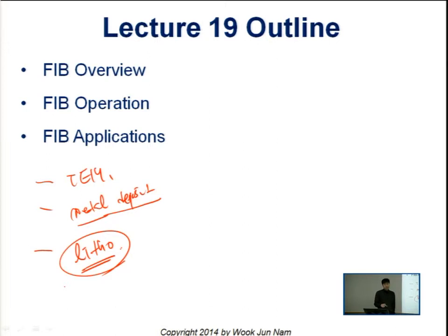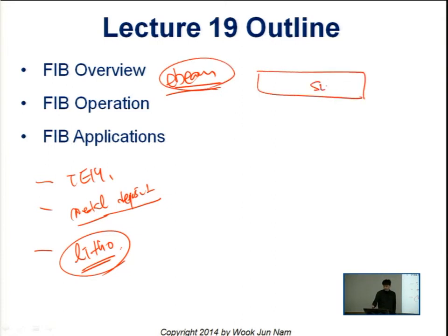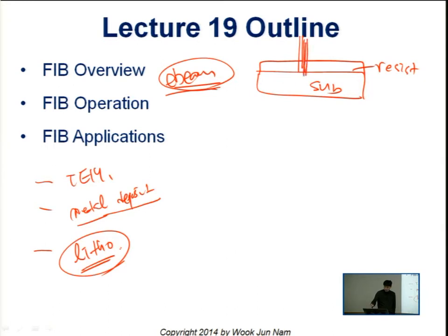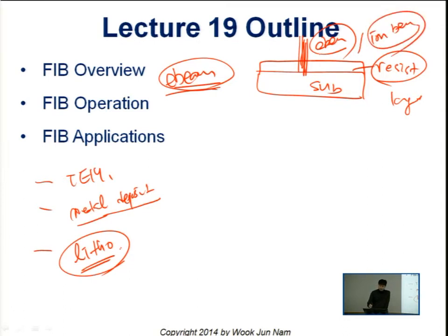The techniques we discussed for E-beam lithography are very similar: on a substrate with spin-coated resist, as we write on the resist layer, we can simply switch this electron beam to the ion beam. And then the exposed area, depending on the type of the resist, we can remove, or we can keep the exposed area.